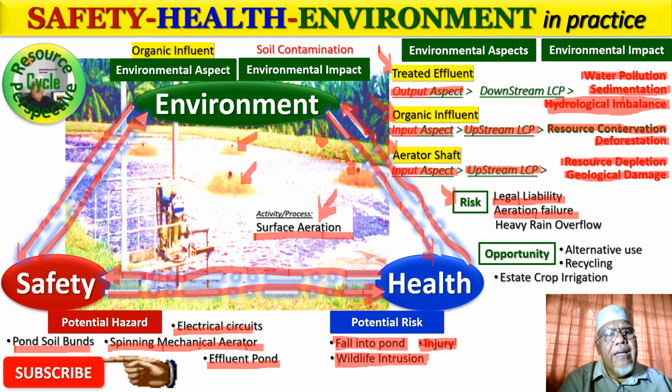And when there is less dissolved oxygen, what would happen? An anoxic condition would develop, and aerobic bacteria will be less in population. It will be taken over by perhaps facultative bacteria, and the process of denitrification will overwhelm nitrification, therefore releasing more nitrogen, which is actually good.